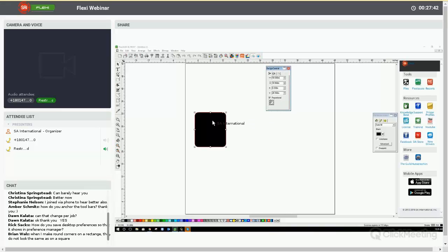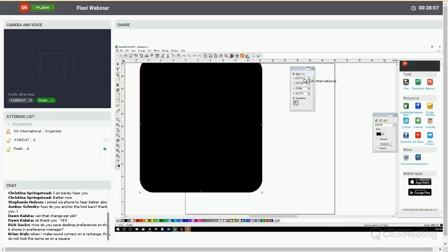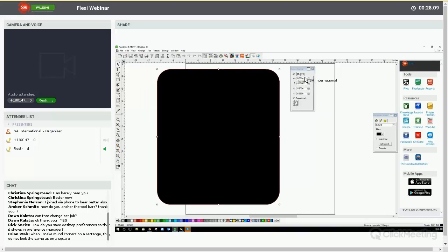Further, let's say I'm designing something for a customer and they're working in metric, and they want a design to be 1 meter long or 2 meters long. I can go online and Google what 2 meters is in inches if I'm used to working in imperial units, or I can just come here and type 1M and hit Enter, and here's my object. This is exactly 1 meter, and it's telling me what that is in the units that are default for me. If I change this to meters, you'll see it's exactly 1 meter.